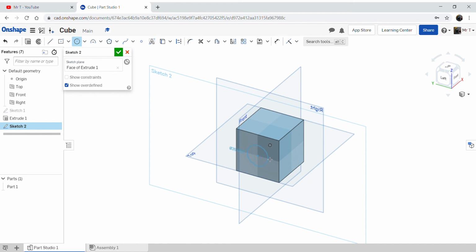I'm looking for a radius, sorry, not a radius, a diameter of 20 millimeters. So I'm just going to, again, something a bit like it, 22, that'll do. And I'm going to press D again, like I did before. Again, that tool gets selected. I can then select the circle and drag away from it. That's now giving me a measurement there. So if I change that to 20 millimeters, that'll auto size the hole for me. Okay, so I'm pretty happy with that.